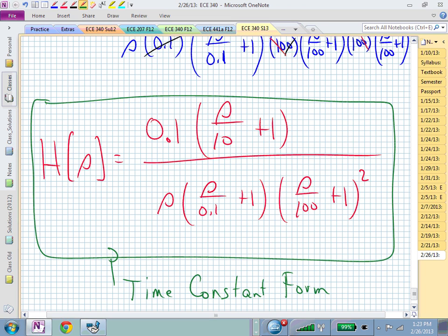We have a term like this. This is called a linear factor. It's just an s to the 1. So we have to learn how to sketch linear factors, either upstairs, zero factors, or pole factors. We could actually have complex roots, and that would give us a quadratic factor. And we need to learn how to sketch quadratic factors, and I'm going to provide you with an oversimplification of how to sketch those. It's not what it really does, but it allows us to quickly sketch with straight lines what's going on in the limits.